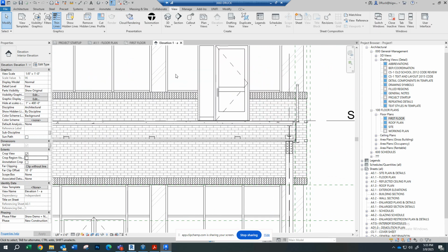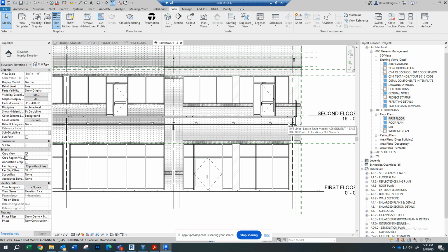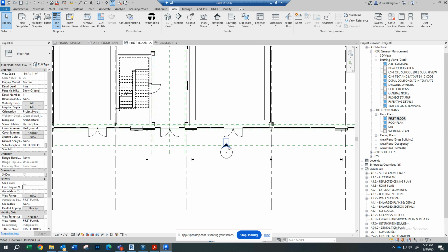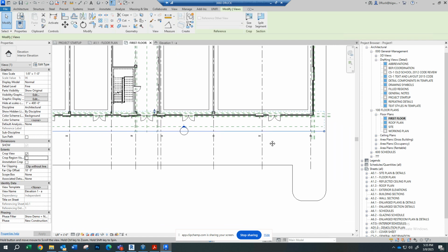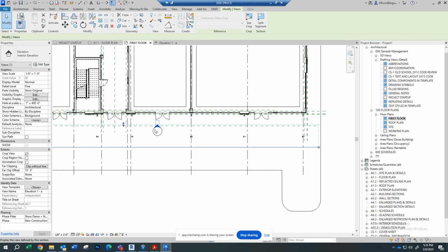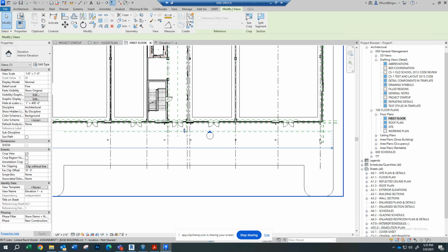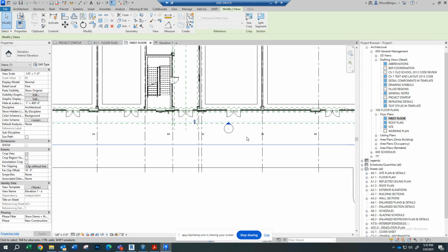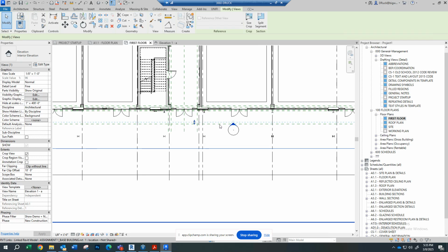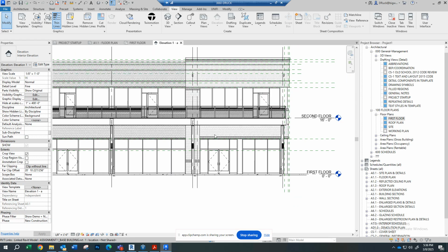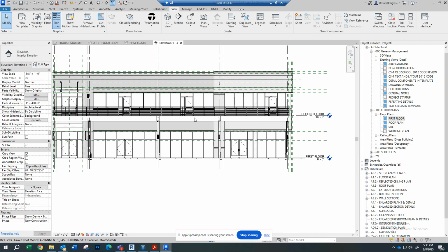What also appears to be happening is the elevation is cutting through the deck, which we do not want. So I'm actually going to move the cut plane back. So the edge of the deck is aligned with these columns more or less. So I want to make sure that they are recessed. The view plane is recessed from that so that it's not cutting through, but rather just viewing it. So if I go back to that view, now we can see a nice clean elevation.